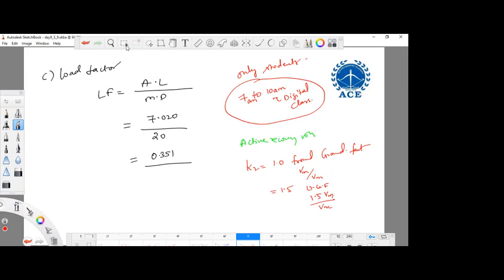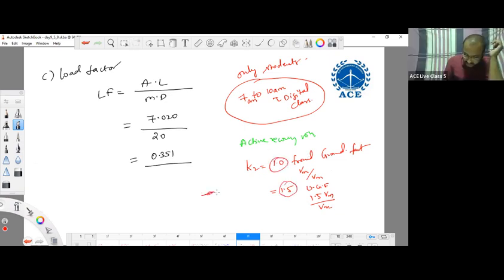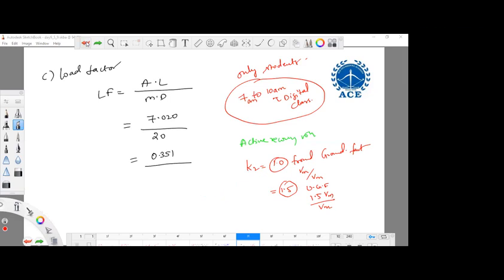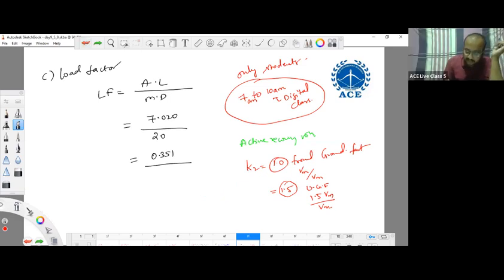Sir, how I got that 1.5, I understood, but what does the term pole to clear mean? First pole to clear means, out of 3 poles, the first pole which is clearing first. Pole means the breaker pole only, the contacts. The first pole which is operating. That is the meaning of that.